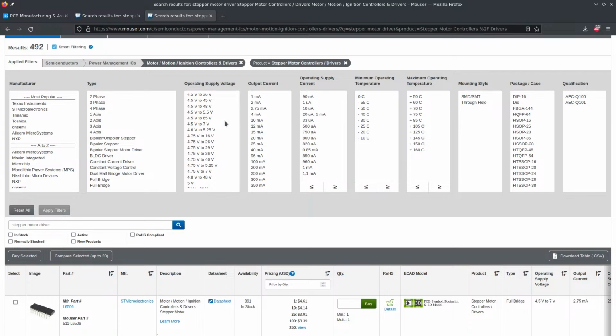But anyways, your RL constant on current is going to have your exponential curve in there. The higher voltage you have, the more you're going to get that to shoot up. So at 5 volts, I'm pretty sure with the internal resistance on these, and this is actually in the data sheet, you literally just Google that. When you go look it up, it'll tell you what the inductance is. It'll tell you what the DC resistance is for each coil, and it will tell you what the voltage for full current is. So that's if you just sat with a DC supply.